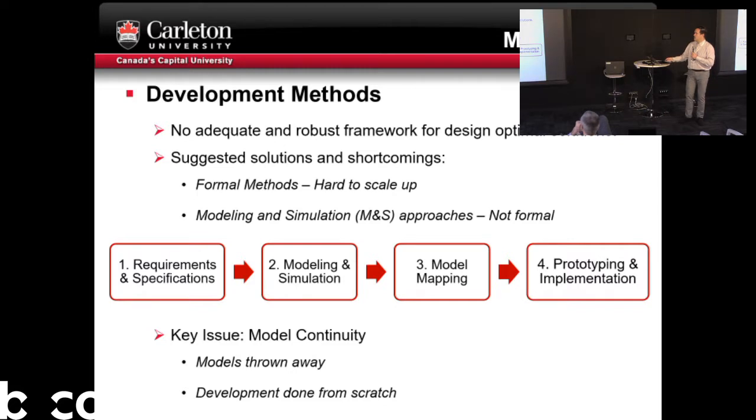As we said, formal methods are hard to scale up, but something that we have seen in the field is that people use modeling and simulation instead. So instead of developing an application based on a formal mathematical specification and proofs, they get a semi-formal specification and they do simulations exhaustively to see how the system will behave, and then you gain some knowledge about the system. You get to know about the control system, the controlled system, the physical environment, and you get to build your application based on simulation.